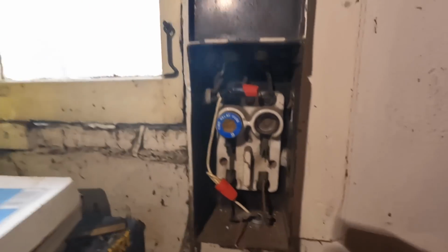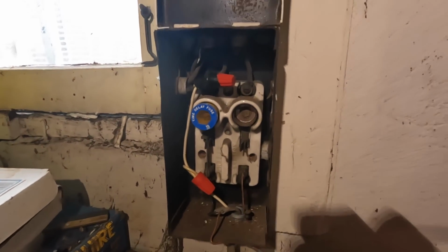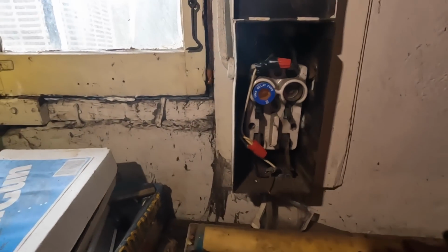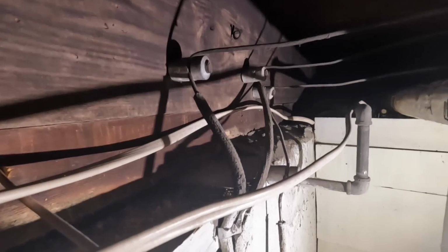This right here was an old Edison base fuse panel that actually went out to the garage. There's a piece of UF cable at the bottom that goes out to the garage, and that was working. I found out that it was actually connected to a switch in the kitchen, and the switch was taped off so that nobody would inadvertently mess with the switch and turn off the power to the garage. Why it was like that, I don't know, but we'll be getting rid of that and all that knob and tube, including that old sub panel that's there, and resupplying a circuit for the garage.